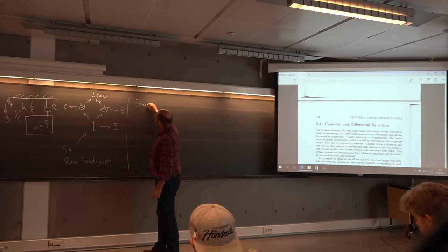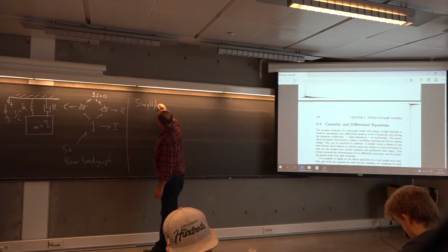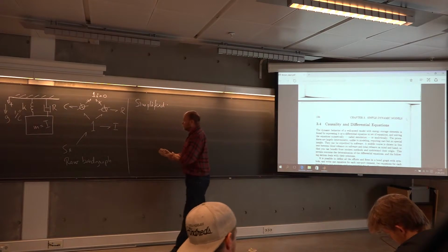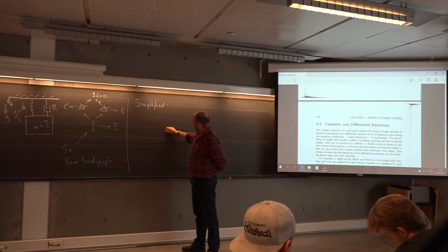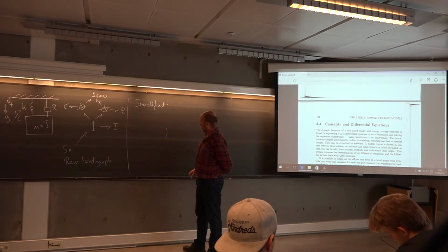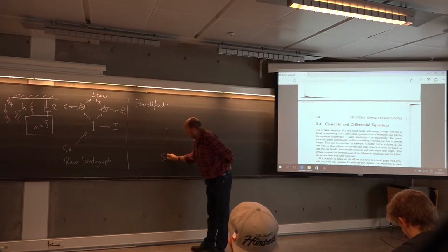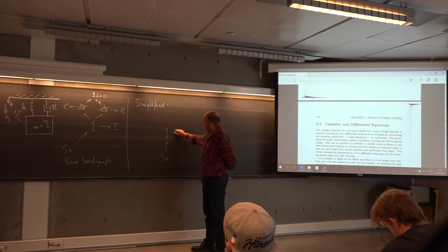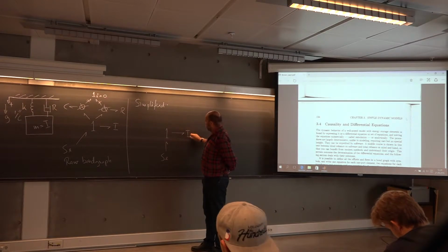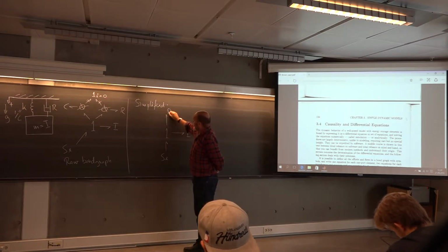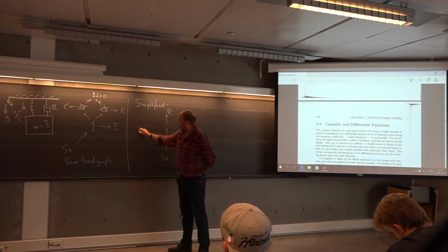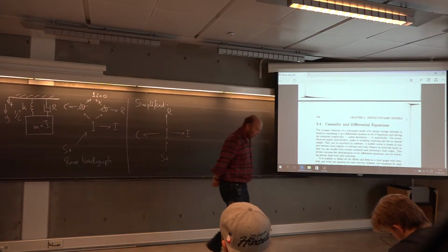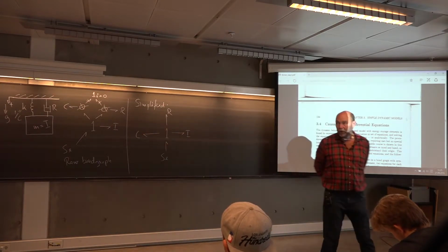So simplified, it should then look something like this. We have a 1 junction, and here we have gravity attacking, and here inertance, up here resistance, and finally a spring. So that's the simplified bond graph.